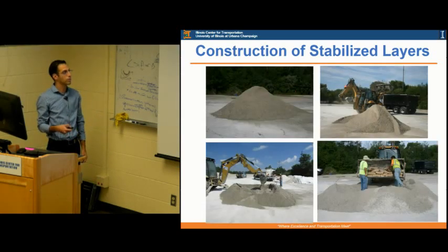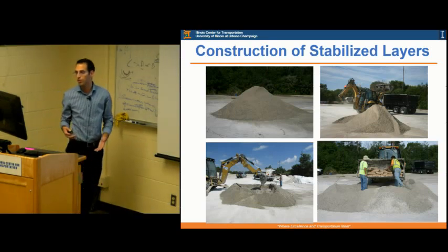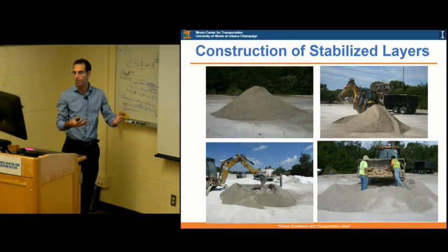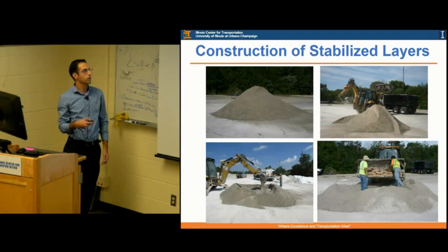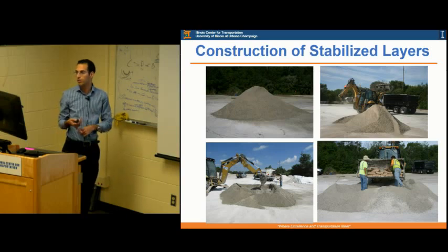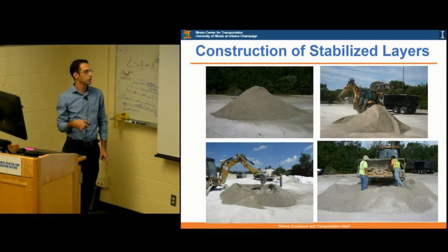So basically, we have the stockpiles outside, and we were sampling those stockpiles from different locations, creating one big stockpile, then mixing that stockpile together from the bucket of a backhoe, and after that, collecting some moisture cups to estimate the moisture content, and some buckets to estimate the loose weight of the material. So we have the loose weight of the material, we can calculate the density. We know the amount being put here because we know the volume of the bucket load.